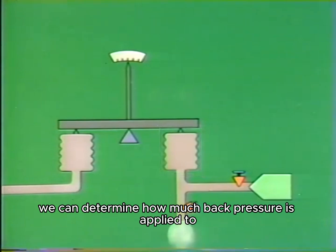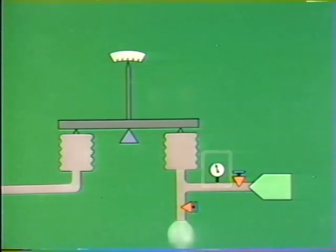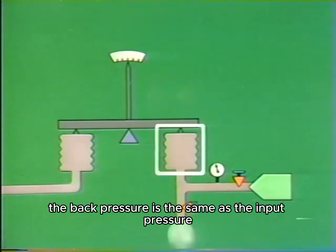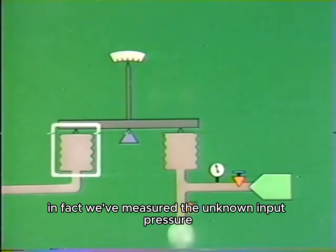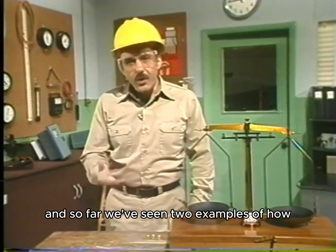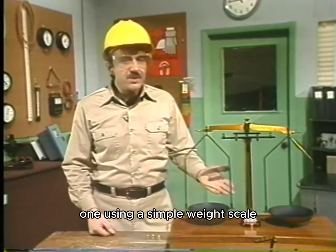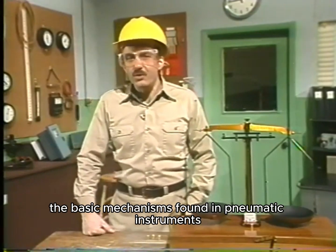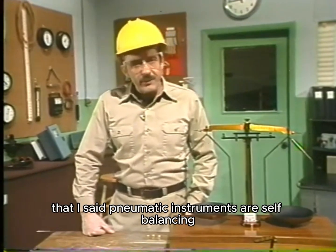Now we can determine how much back pressure is applied to the balancing bellows by adding an accurate pressure gauge. When this instrument is balanced, as indicated by the error detector, the back pressure is the same as the input pressure. In effect, we've measured the unknown input pressure by measuring the back pressure. And so far, we've seen two examples of how the balancing principle works. One using a simple weight scale, and the other using an illustration to identify the basic mechanisms found in pneumatic instruments.